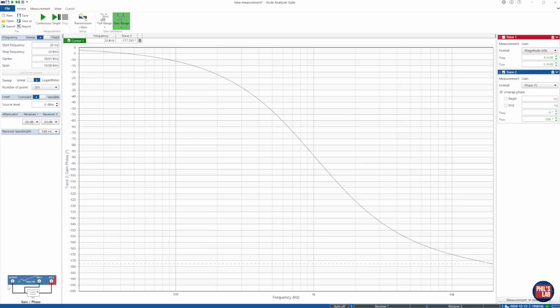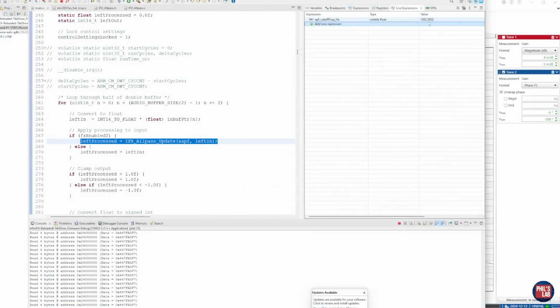Now, with our cutoff frequency set, as we just saw at 1 kHz, we should expect our phase delay, or phase, to be -90 degrees at that cutoff frequency. I can change the marker to go to -90 degrees, and that gives us exactly 1.022 kilohertz at -90 degrees. And if we look at our current setting, that's exactly at 1.022 kilohertz. So our filter is performing as it should.